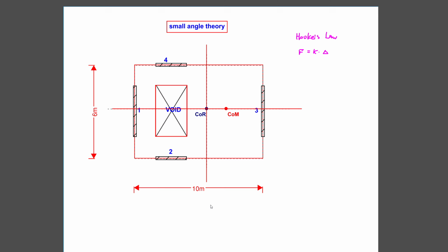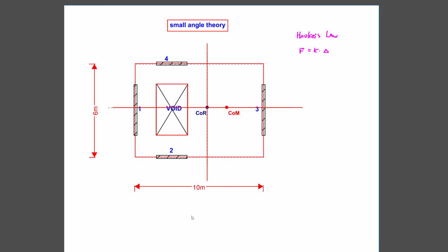The torsion, remember 1170.5, we have to do a compulsory 10% eccentricity, that is accidental. So imagine our earthquake force is heading this way, 100% heading this way, north and south direction. And also we are allowing for a 10% eccentricity hitting my floor plate, causing my floor plate to twist back and forth.